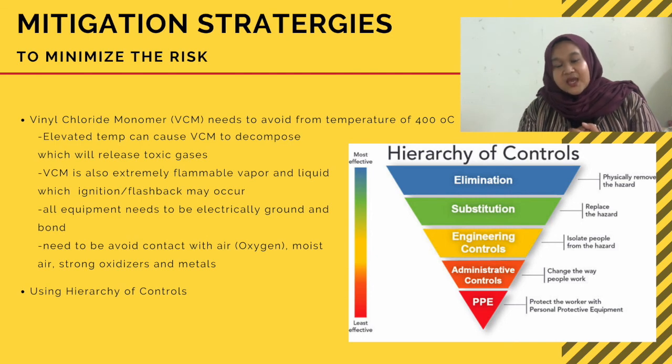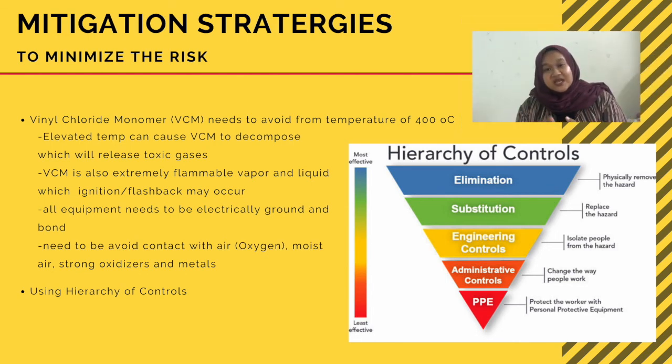And then VCM is also an extremely flammable vapor and liquid, which ignition and flashback can occur due to that. So in order to prevent that, all the equipment needs to be electrically grounded and bonded, and VCM needs to be kept away from contact with air, which is oxygen, moist air, strong oxidizers, and metals.